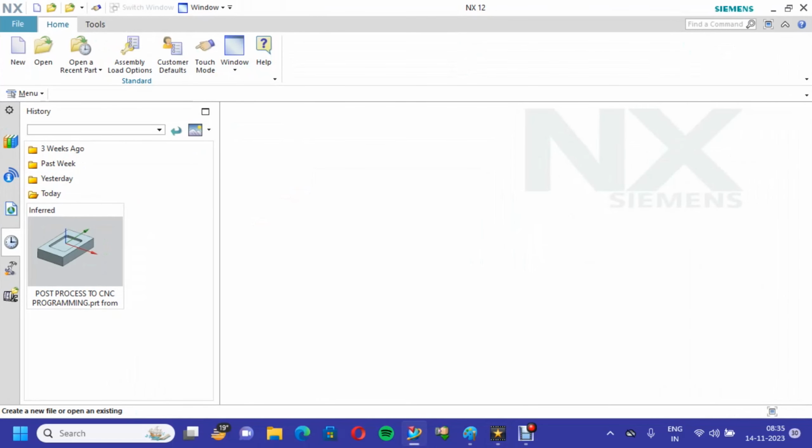In this class, we will discuss how to generate G codes and M codes for CNC milling programming. We can say post processing. It is one of the most important things, how to do post processing for your available controls. Somebody has FANUC control, Heidenhain, or Siemens control. According to your machine controls, you have to create post processing. Then we can edit the post processing as per your machine requirement.